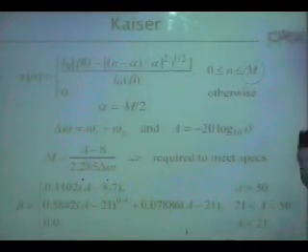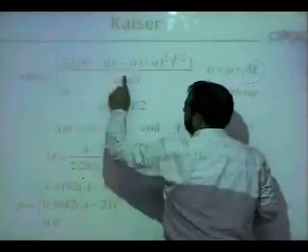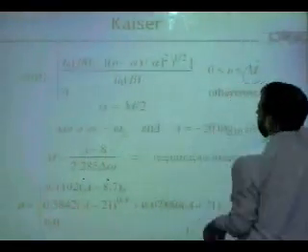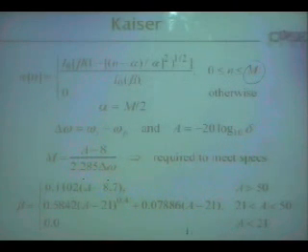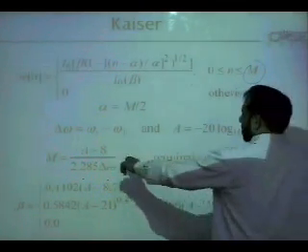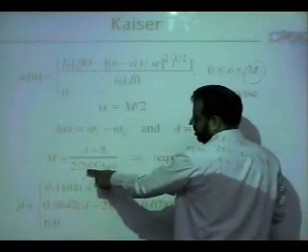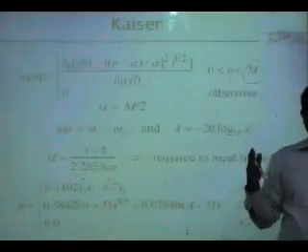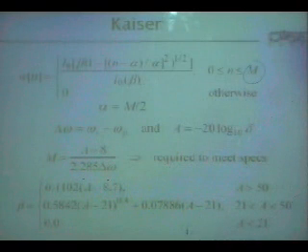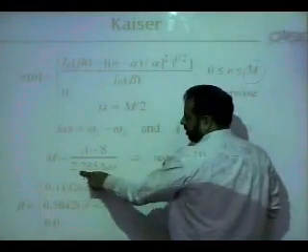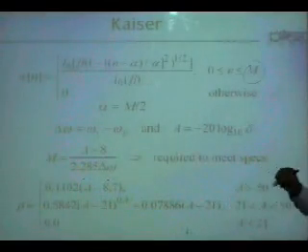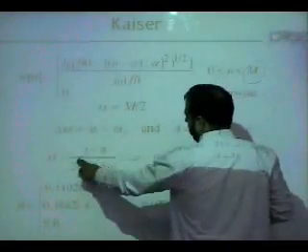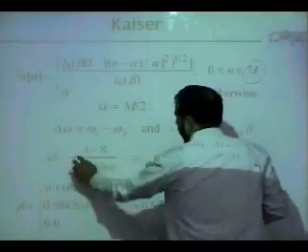But here you need to know beta and alpha. Alpha is simple, but you need to know beta. So beta is the design parameter. First of all, how do you compute the length? The length is computed using empirical formulas. What is an empirical formula? Kaiser tried several things and came up with these magical numbers. So these are just numbers, no rationale, no math. It's an empirical number, 2.285. He says put this in, and (A minus 8) divided by (2.285 times delta omega) will give you an M.